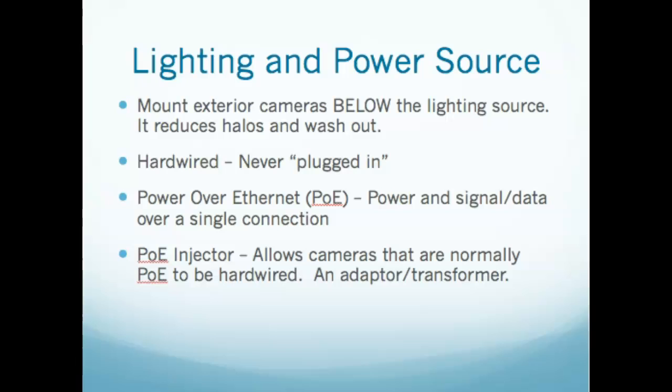So just know that oftentimes someone will say, well, you have a PoE camera here, and you're going to put cameras in your new building, and even though you don't need this one anymore, you can't reuse it because you don't have any network out in the other building. You can get PoE injectors, saves you a ton of money, and you can reuse cameras. And you should always reuse cameras when you can, right? When your facility changes, when your mission changes and you don't need cameras in a certain area anymore, you take them down and you reuse them somewhere else when the need applies.